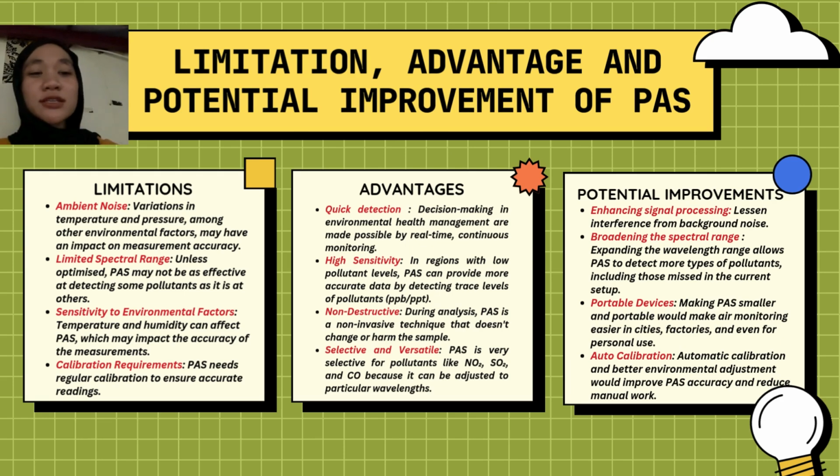So, one limitation of PAS is ambient noise. Environmental factors like temperature, humidity, and also pressure can interfere with the measurement, making it less accurate in certain conditions. Another issue that we can see from PAS is its limited spectral range, meaning that PAS may not detect all types of pollutants, especially those that don't absorb well in the mid